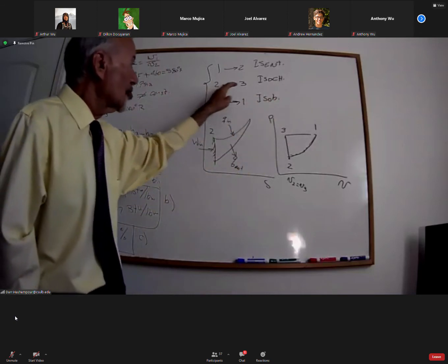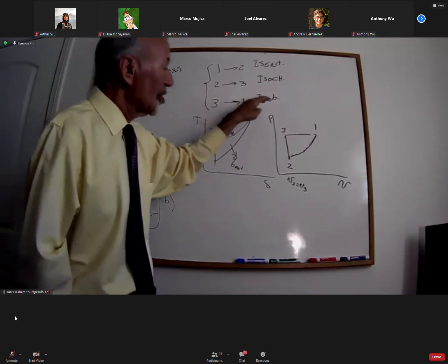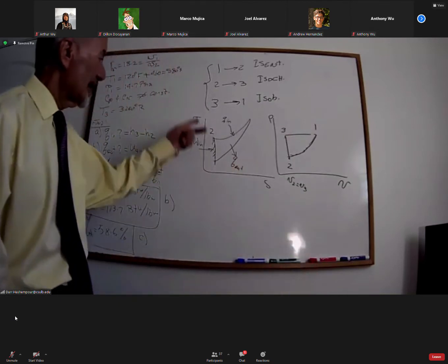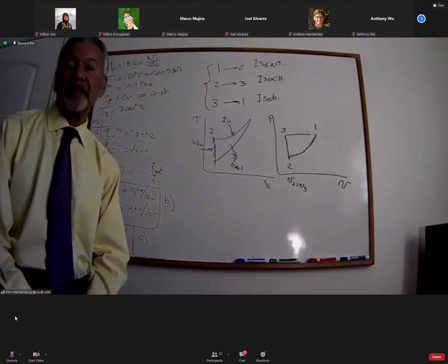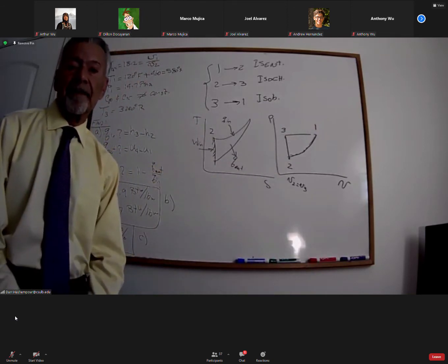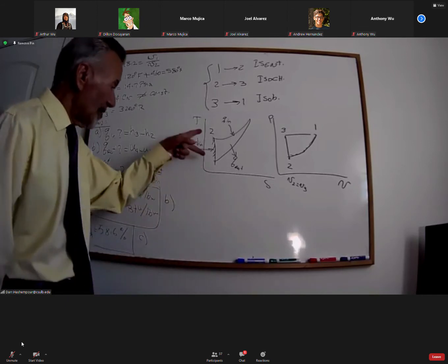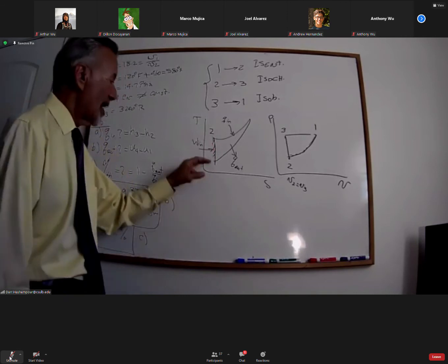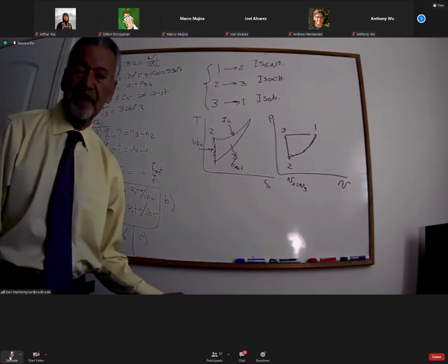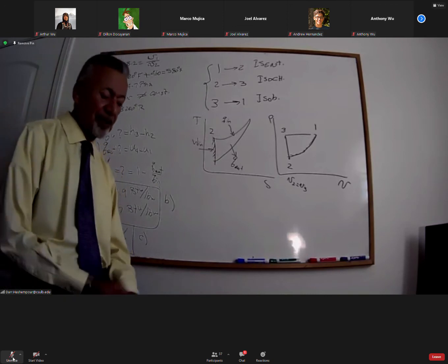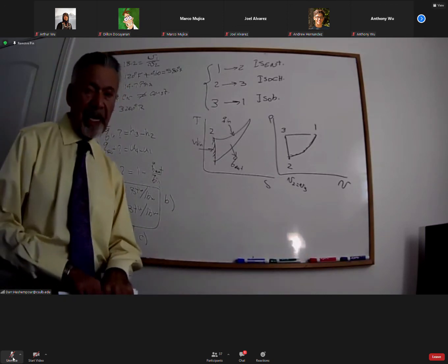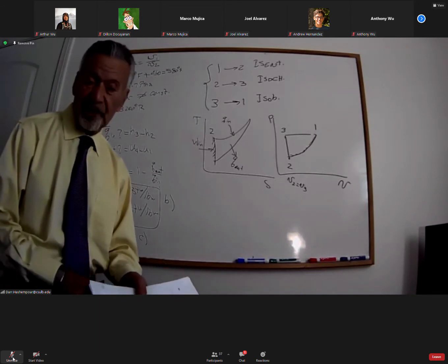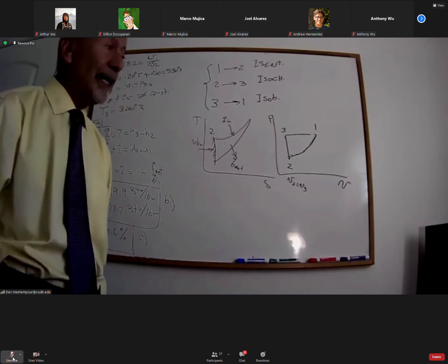Sometimes they say 2 to 3 is heat addition, 3 to 1 is also heat addition. Whatever they say, it doesn't matter. At the end of the day, that would be the TS and PV diagram. But you're right. Every time we have an isentropic process, it's either work in or work out. You cannot have an isentropic heat addition. That's not going to happen because isentropics are for compression and for expansion. Any questions on that?